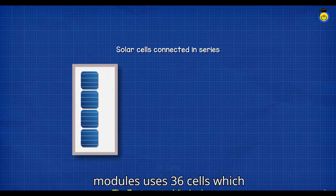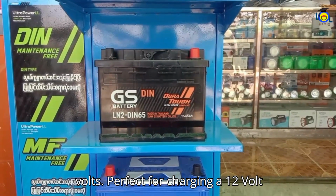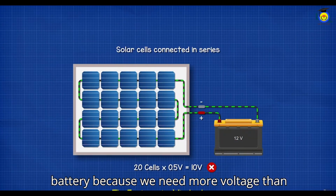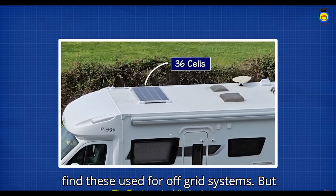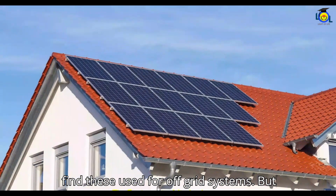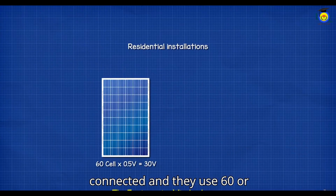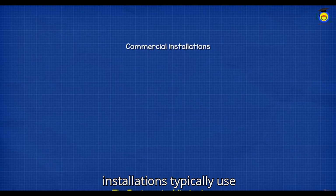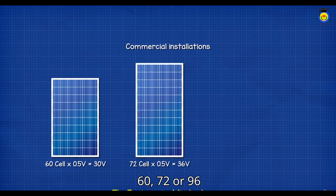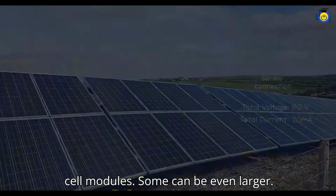Small modules use 36 cells, which produces around 18 to 19.8 volts, perfect for charging a 12-volt battery because we need more voltage than the battery to charge it. So we often find these used for off-grid systems. But most residential installations are grid connected and they use 60 or 72 cell modules. Commercial installations typically use 60, 72, or 96 cell modules. Some can be even larger.